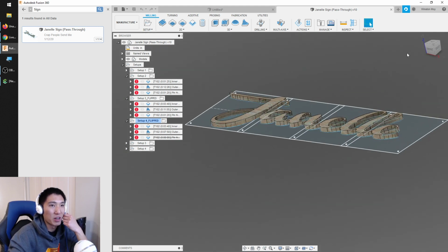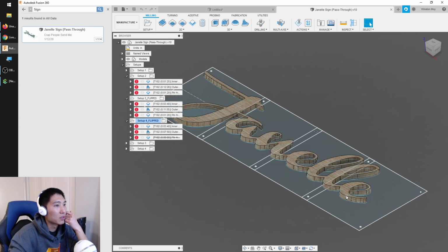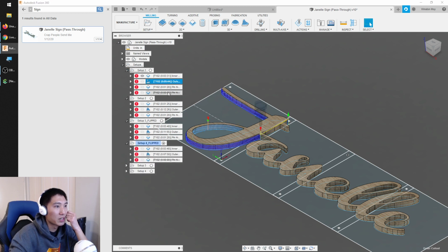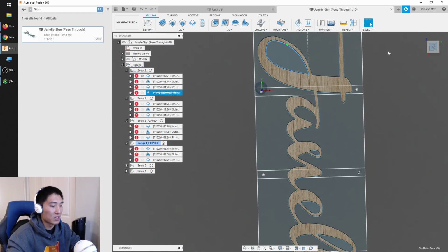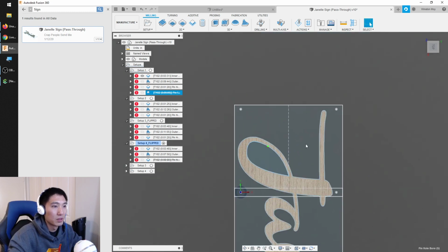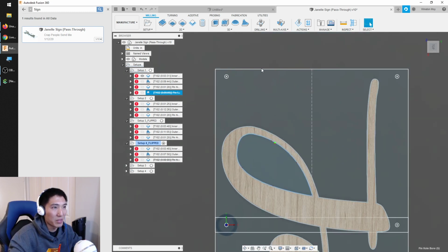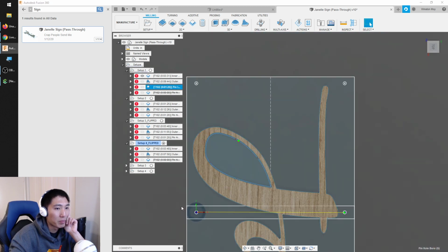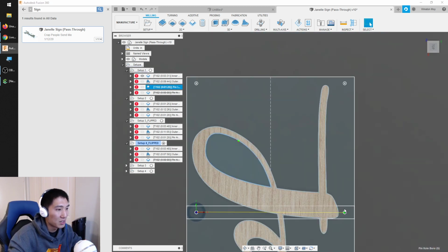So this was a sign that I made for my buddy George, and the way this works is you cut in sections at a time. In the first section, you'll cut the top area. This is a containment boundary. It restricts the cutting area to what fits on the stock Shapeoko 3, and then I drill pinholes in the bottom. And then when I'm ready, I have 2 matching holes in the wasteboard, like that would be up here.